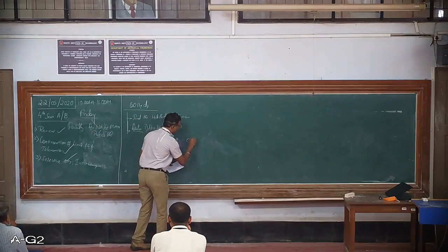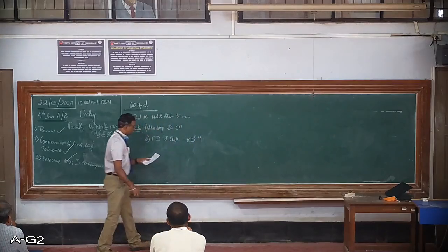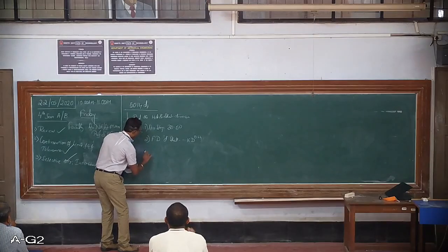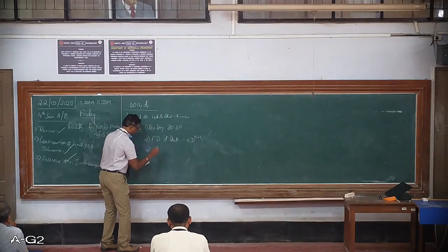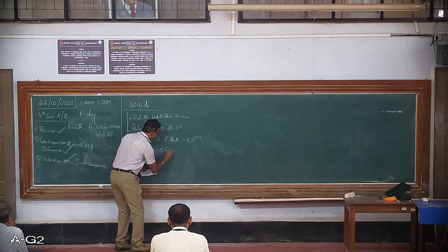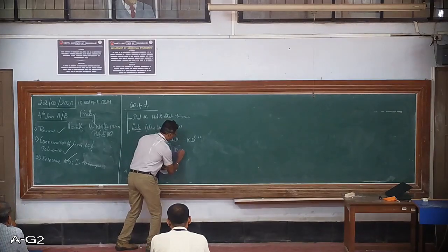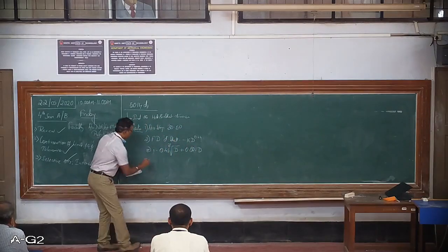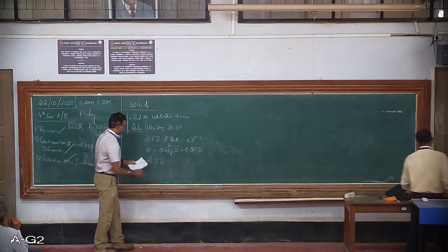Next, the fundamental tolerance value, I, the third one: I equals 0.45 times the cube root of D plus 0.001 D. Next, the fourth value that is given is the IT tolerance grade: IT6 equals 10i.